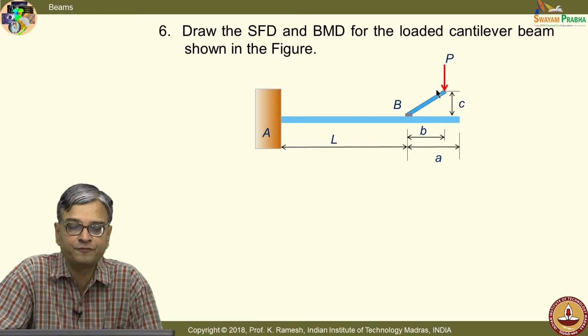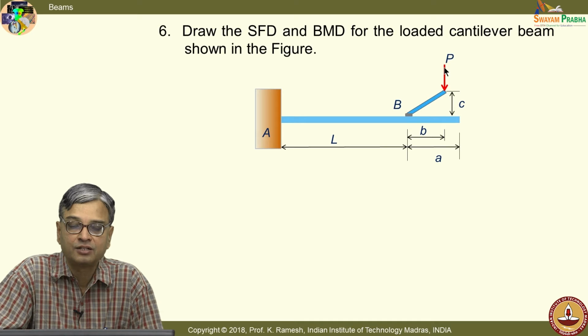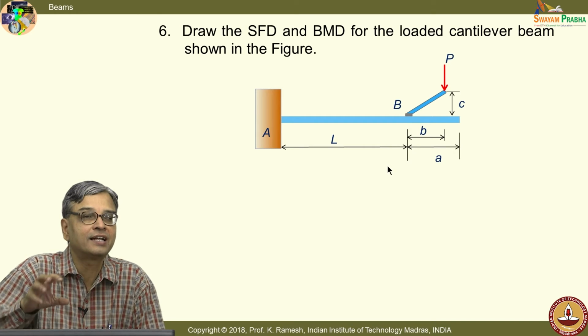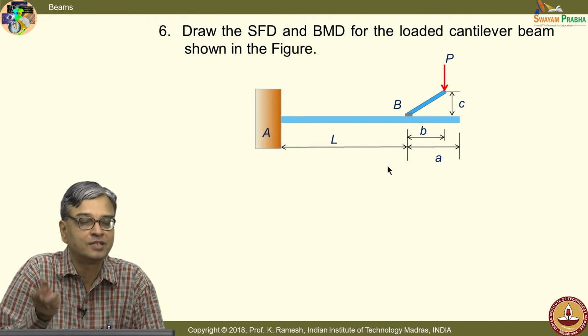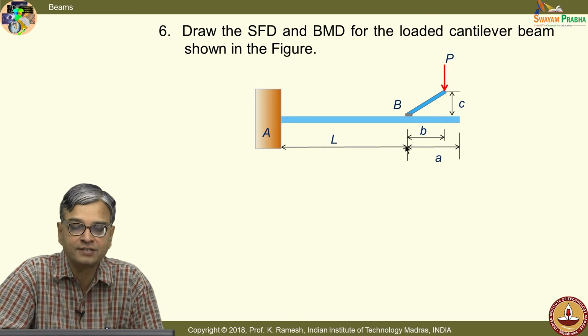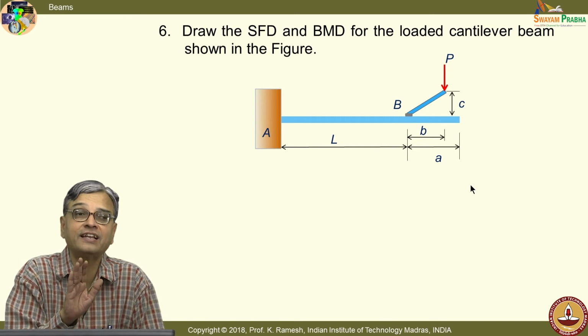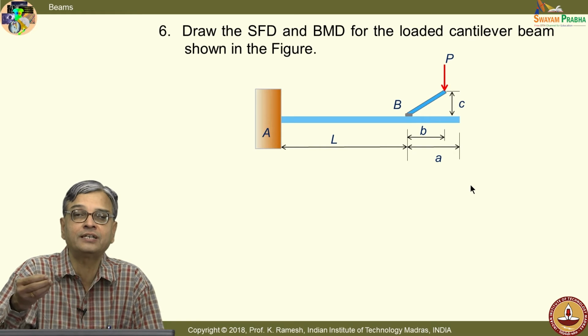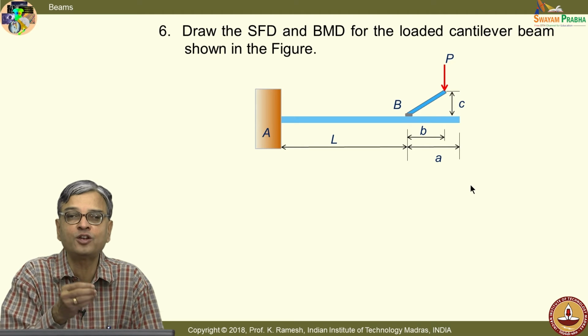So, when I translate this force to point B, what will be the force interaction at point B? You have to put a force and then cancel that force, recognizing the other two forces forming a couple. So, I would have a force as well as a couple. Is the idea clear? This you have to recognize. When I have any protrusion where I apply the load, the loading is a little involved, so you have to interpret the load first.